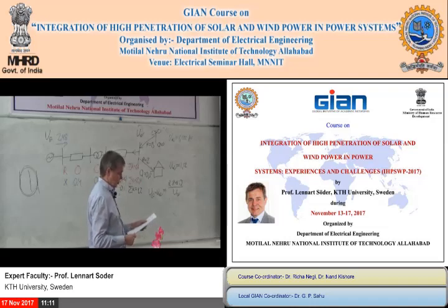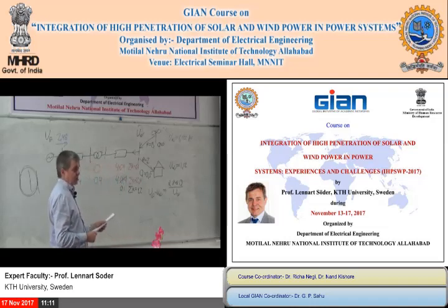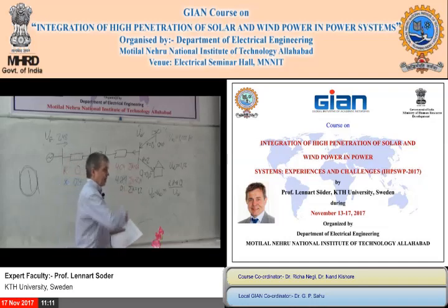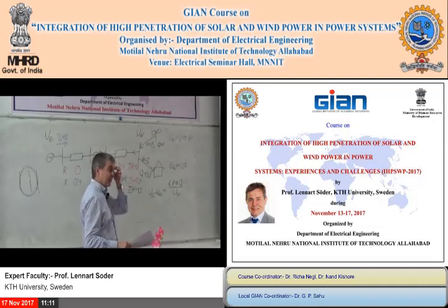Can wind power contribute? Yes, wind power is a bit better than solar. In wind power, you have an inertia. Of course, if you have the conventional type, the star type, where you have an induction machine directly connected to the grid, then you have some inertia, but that is very small. You have a small contribution because of the slip, but it is not so big. But the modern type of wind turbines normally have a converter.